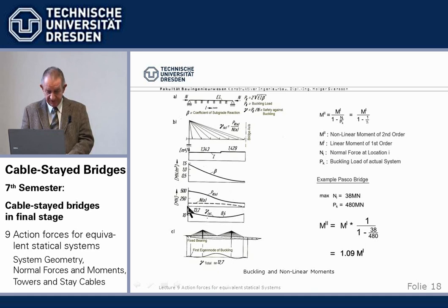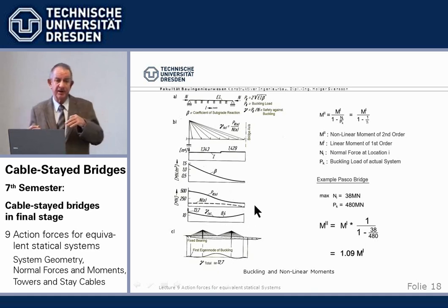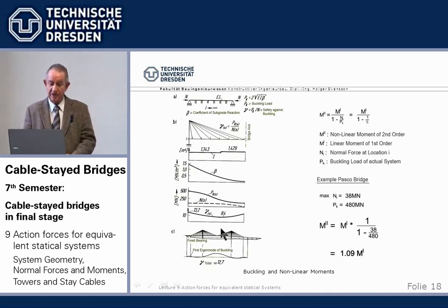It runs something like that. And then you can show generally that the overall buckling safety compared with this additional system is very close to the tower. So if we take this, we had here 13, and the true computer calculated buckling stiffness 12.7, close enough. So if we use the support, normal force, and stiffness at the tower, with this formula, we can immediately by hand calculate the buckling stiffness of the beam.